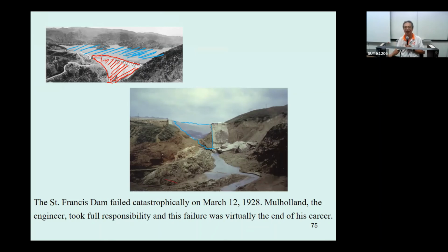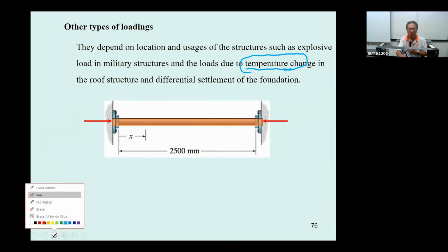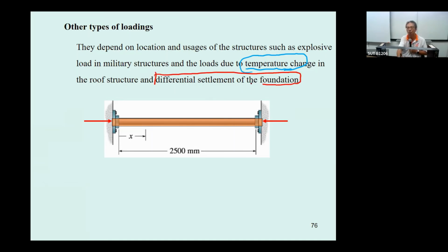Okay, and let's add more. Not only that, think about the roof of the building. What does it get? It gets the sunlight during the daytime. It's hot. When the structure is hot, the structure will expand. When the structure expands, there is load inside it.